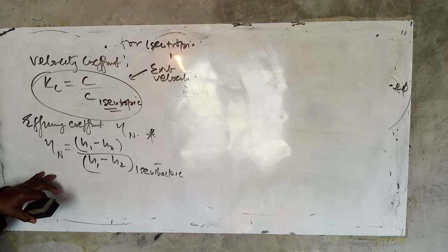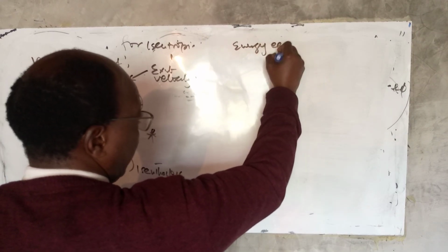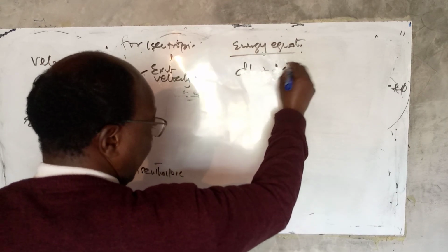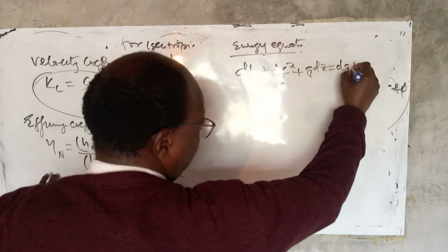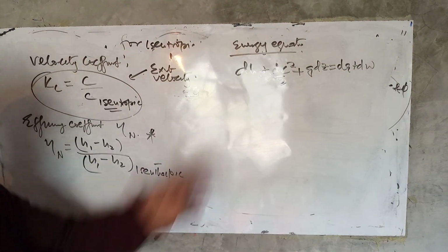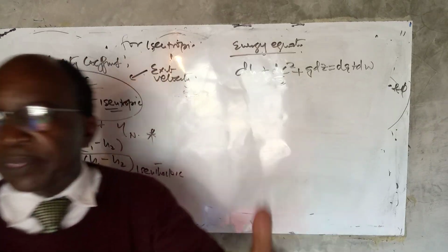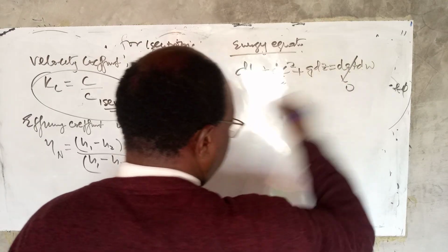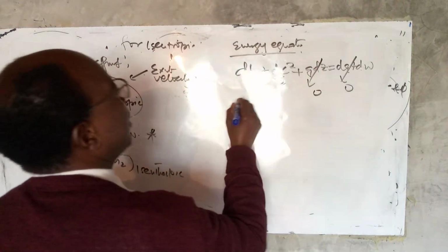I want you to remember the energy equation: dH plus dc squared over 2 plus g dz is equal to dq plus dw. And this should now be an equation which should be stuck in you, because you have to operate with it. So we know that is 0. Also, when we say that if the datum level is not significant, that would be 0. So dh